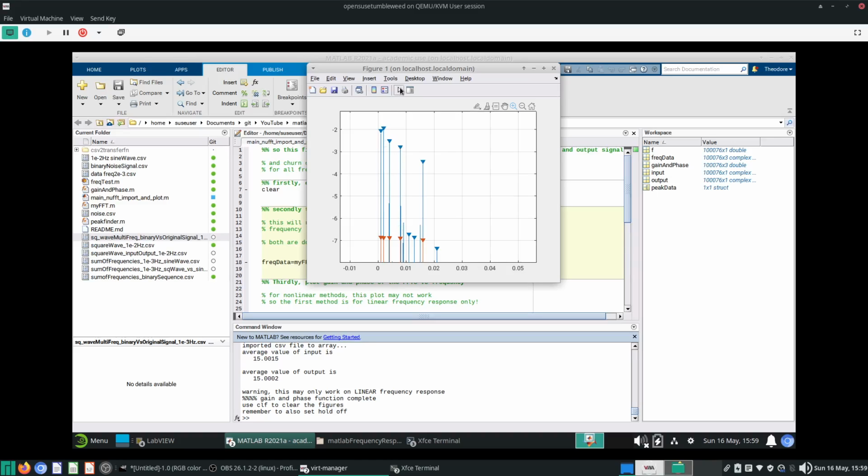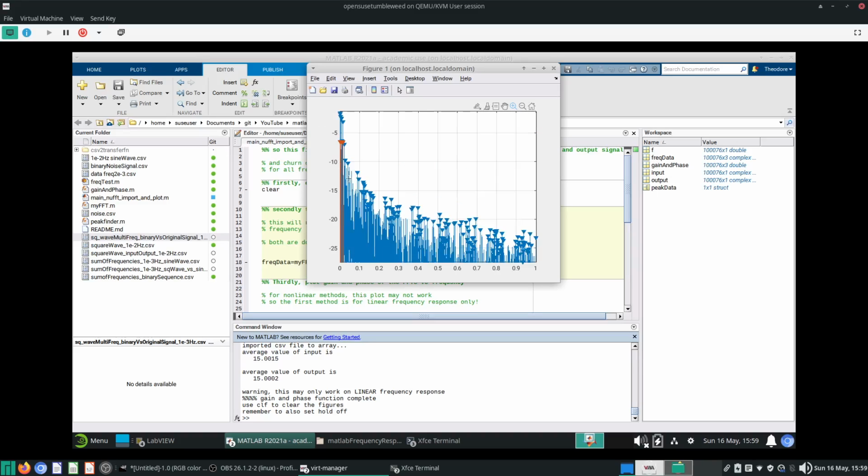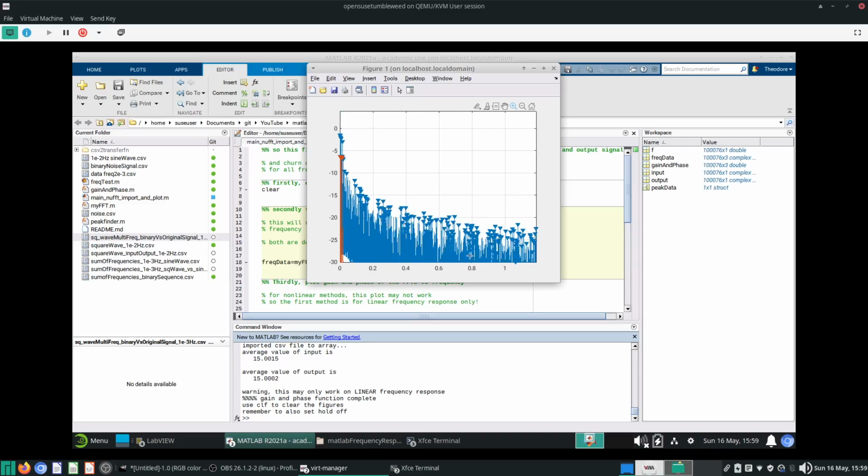But if you can't use sine waves, as we can see from the results here in the Fourier transforms, the strongest signals are way above background noise. The strongest signals are your signals of interest. So a binary approximation of square waves actually does pretty well. Because you have all of these other peaks as well, which you may or may not want.